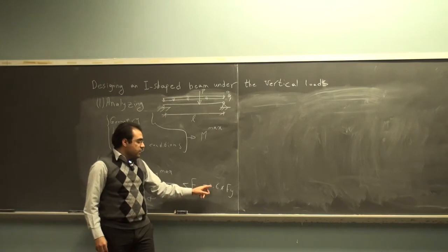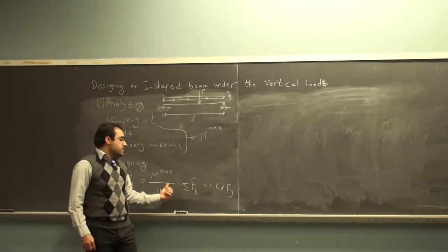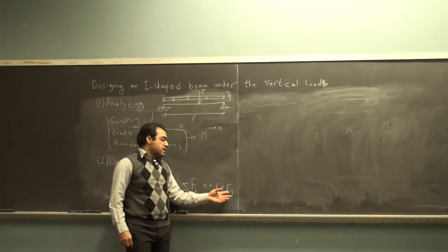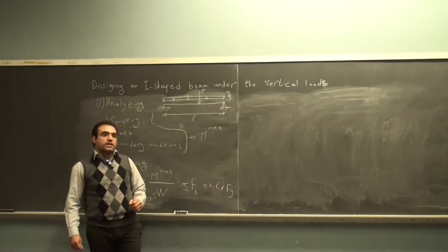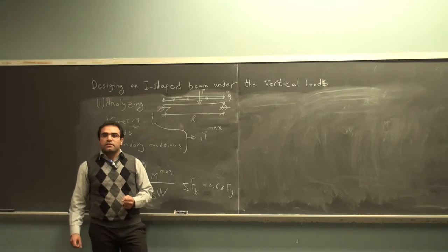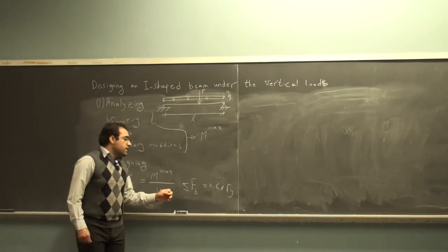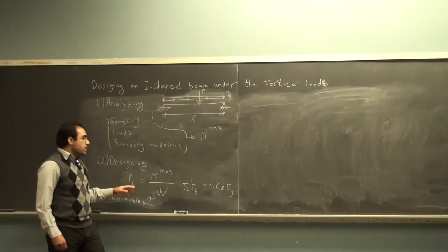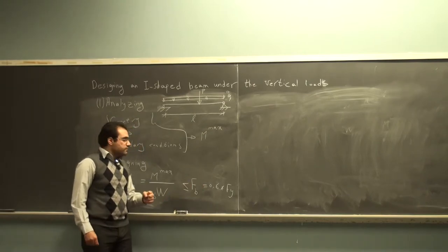So we multiply it by 0.6 to find the allowable bending stress. But we have actually multiplied this yield stress with a number that is less than 1. Can you guess why we have done it? Any idea about it? Does it work as a safety factor? Exactly, because we want to make sure that the beam is strong enough and the design is safe. So we multiply the yield stress with a number that is less than 1.